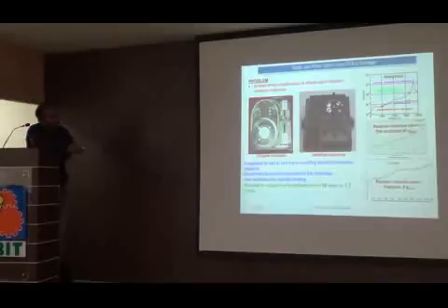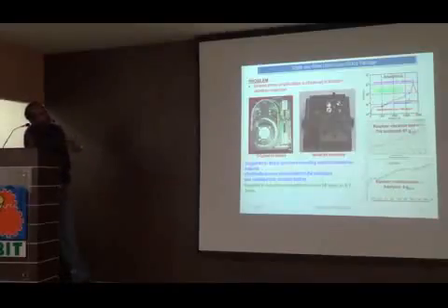To check our design, we even did a test on another dummy unit, and we found the same kind of response was coming. So now we have to change the mounting scheme and other structure so that the amplification reduced from 16 times to 9. This actually resulted in a reduction of the amplification of around 1.7 times.